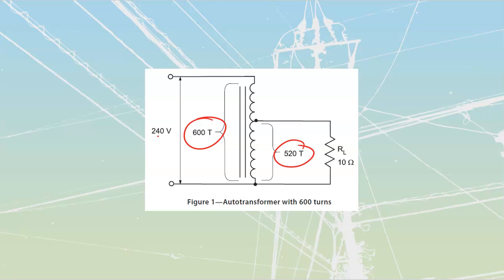What we are going to do is establish the volts per turn. It's going to be a little bit different process than what they're going through inside of theirs, but it just makes a bit more sense to do so. Volts per turn is simply the number of volts that I have on a given side over top of the number of turns on that same side, and then it's going to give us a decimal number. It could be a whole number, it could be a partial number, but then we're able to just translate that into the opposite side. So let's do that off of this one.